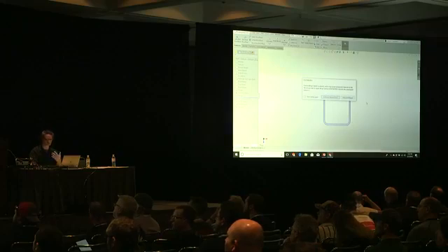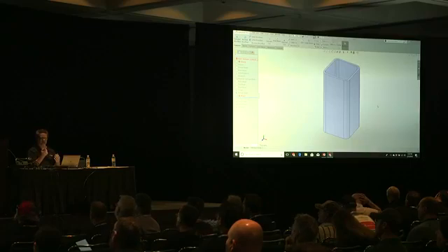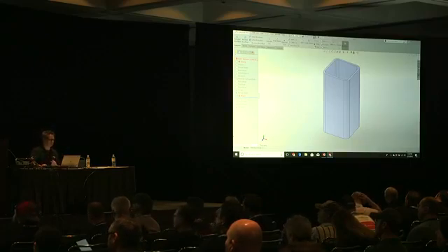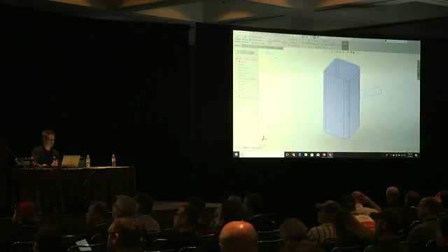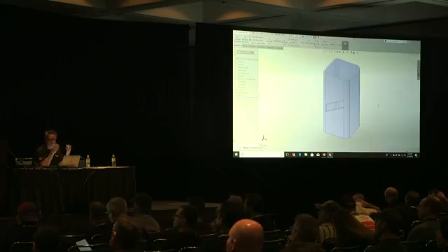Get an error. I'm used to that. I like to break stuff. Continue along. Now the trick is knowing why I got the error. When I did the wrap, I had the cylindrical surface. I'm not using that. I put that to construction. So now I have this square, so all I have to do is edit my wrap, this face. That's the way it always worked. Wrap worked on a single face.